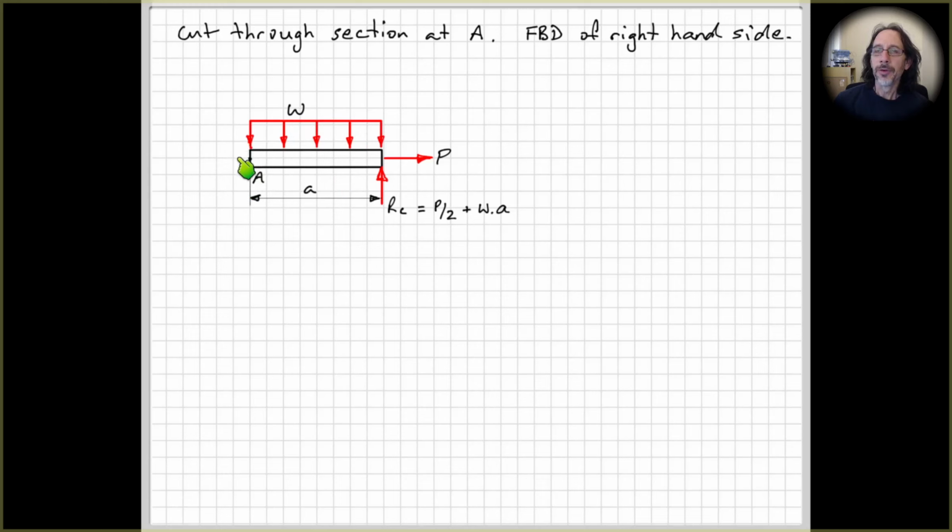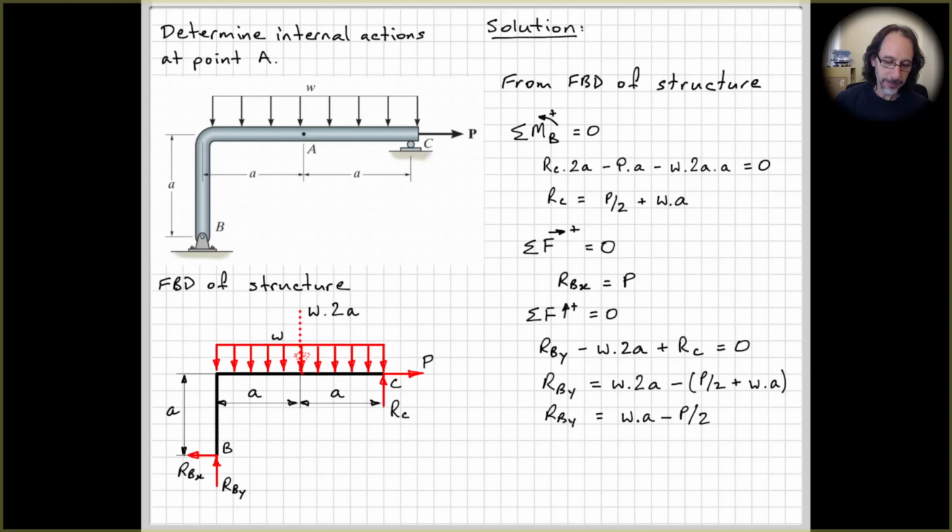Internally now, we're going to have generated here internal actions. So there could be axial force, shear force, bending moment, torsional moment in general, generated in here by these external loads. So if I just go back to my previous drawing again, so what we're trying to imagine is that we've got these loads out here transmitted through the body to our support here. And at each location, in general, the internal actions will change as we go along.